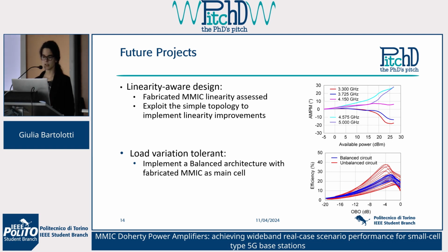Second of all, we checked the performance in the case of load variation. You can see from the red curve of our circuit that the performance in terms of efficiency was varying a lot. What we can do is use the designed circuit as the main cell to build a balanced topology that has proved to improve the load variation performance.